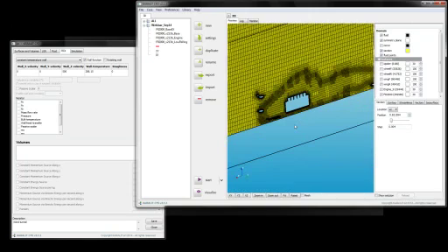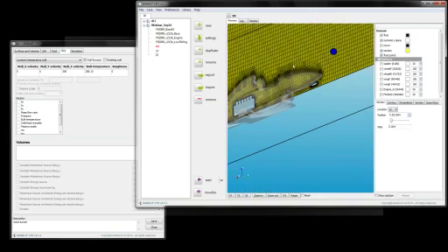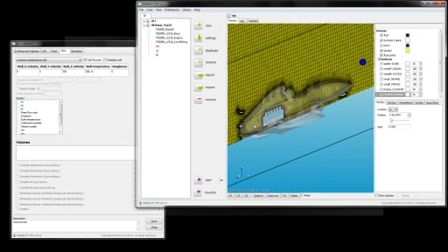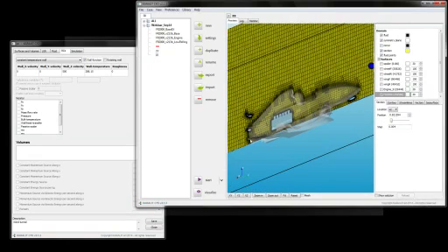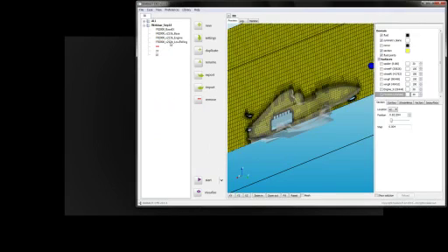So what we have is the mesh around for the aerodynamics calculation around the car being tied to the flow inside the car, and eventually the flow will exit from that exhaust that we opened up. So that's all really one would need to do in terms of setting up that case before one runs it.